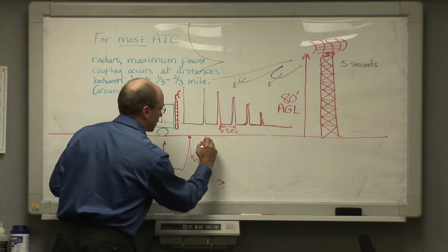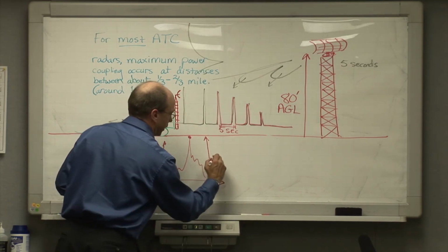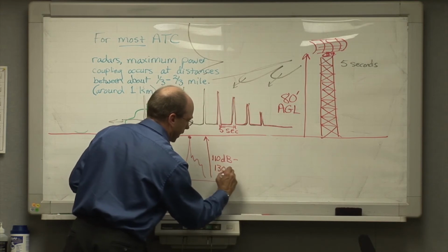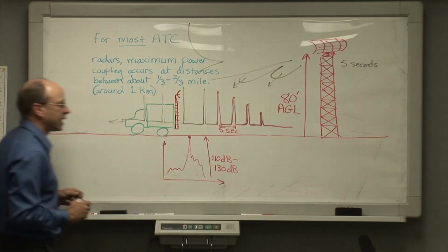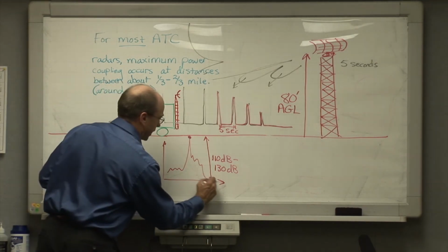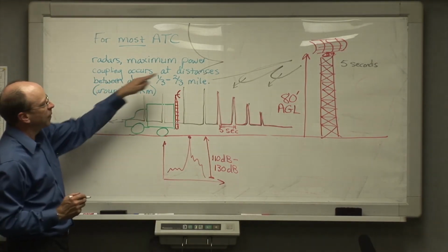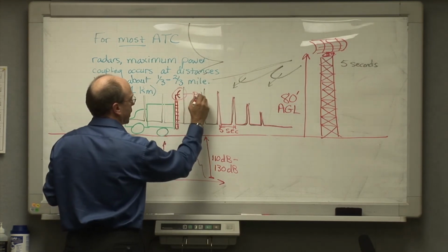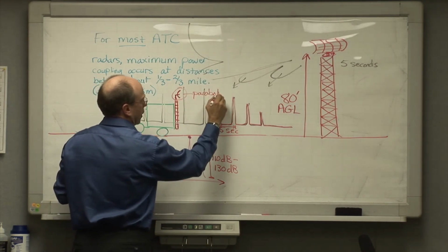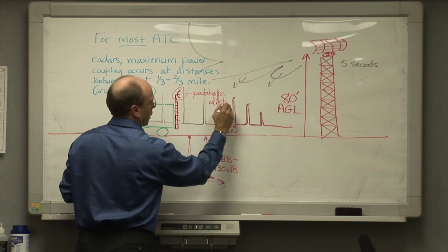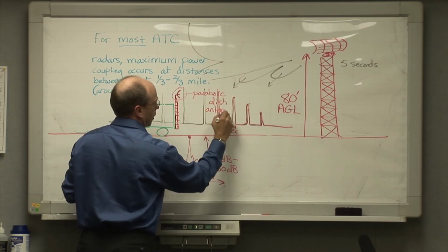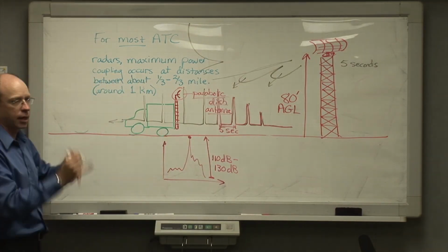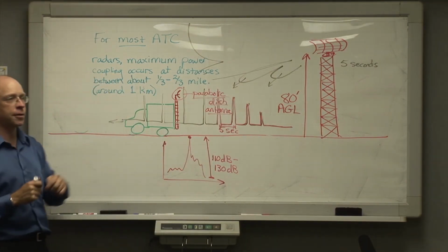And if at all possible, we'd like to get definitely 110 dB, and if possible, ideally, we'd like to get up to 130 dB of dynamic range on that measurement. And we do that by getting to an optimum location, getting the maximum power of the radar, and by using a parabolic dish antenna, typically about 1 meter, again, because that's a good trade-off in terms of gain versus the mechanical weight and size.